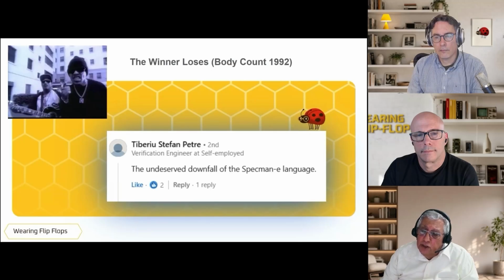And together with the coverage, you will be able to generate those tests overnight and collect the coverage again and see what holes you have again and again. So you don't need random generation. You need just a machine that injects the stimuli into the DUT, and the stimuli are generated by the AI. That's one possible direction. And how do you check that the stimuli and the DUT actually behaved correctly?